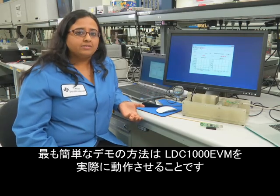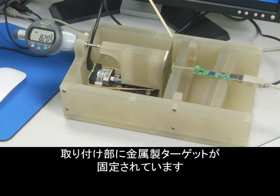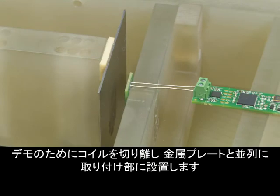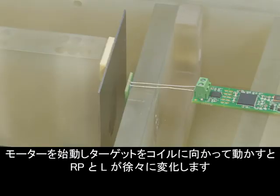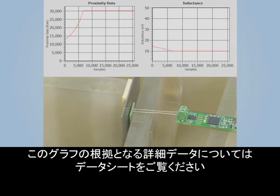The easiest way to demo this is to show you the LDC1000 EVM in action. We have a metal target that is fixed to this mount. The mount will be moved using the stepper motor that's down here. For the purpose of the demo, we snapped off the coil and put it on this mount so that it's parallel to the metal plate. The EVM is connected to the GUI, and you will see the LDC response on the screen. Once we start the motor and move the target towards the coil, you will see the gradual change in RP as well as in L. To get more details behind how these graphs are formed, again, please refer to the datasheet.